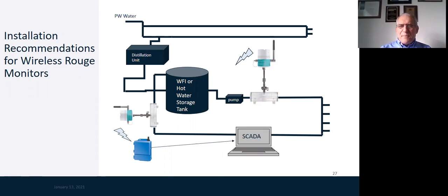Rouge is dependent upon temperature. Rouge is dependent upon your operational characteristics of your water system and your points of use, whether they're open or not. When the water is recirculating with no use points open, the Rouge will develop greater inside the piping. So understanding these dynamics and having the data in order to show what's going on with the water chemistry at any given moment, and the temperature, is going to be indicative of what happens with the Rouge rate.